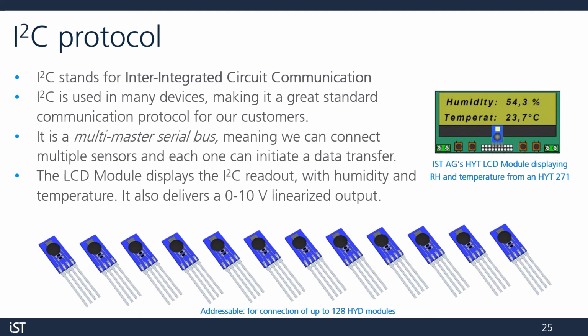Also, I previously mentioned IST's HYT LCD module. With this, you can plug in an HYT 271 or 221 and get a quick readout of RH and temperature. It also delivers a 0 to 10 volt linearized output for easy integration.